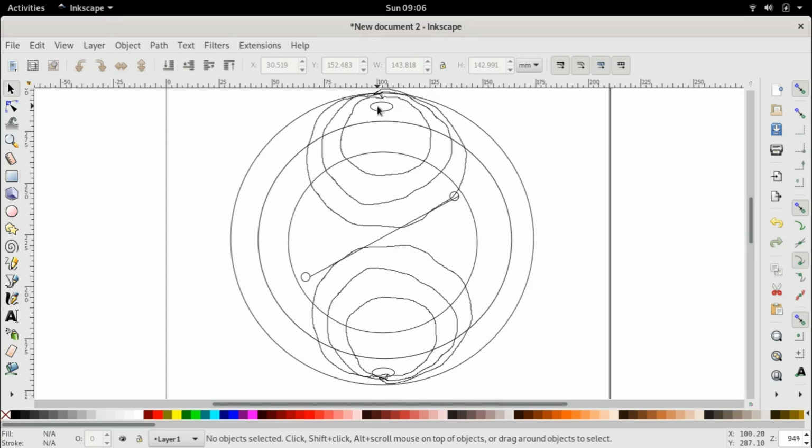So now if I assume that this conductor here, this slot here has conductors where the current is entering the page, then by using the right hand thumb rule we can conclude that these flux lines will be in such a direction that they'll be in the clockwise direction, and therefore in this slot, these flux diagrams produced by the conductors in this slot will be in the counterclockwise direction.